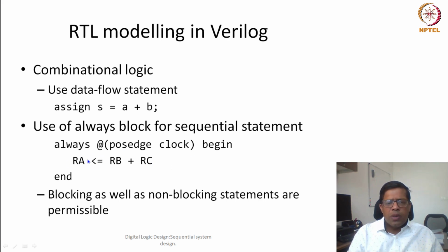This particular statement, if you remember, is called a non-blocking statement. So you may ask, is it only non-blocking statements which are allowed in Verilog if we want to model at RTL level? Then no. Blocking as well as non-blocking statements are both equally permissible.